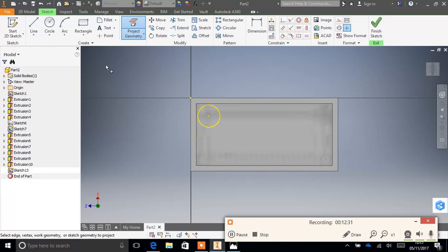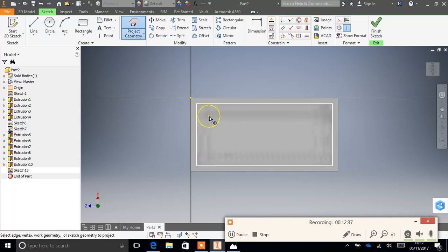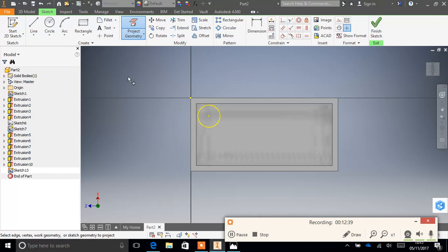What that does is up here on the sketch you can project it, and as you can see where that circle is and where the centre is. So actually forget what I was saying about measuring, use that because you know that you're exactly in the right place. Now I can't remember what size I said those circles were. They are 2.6.